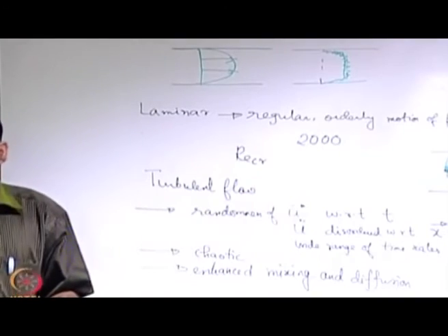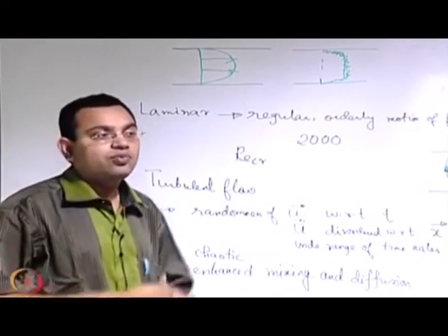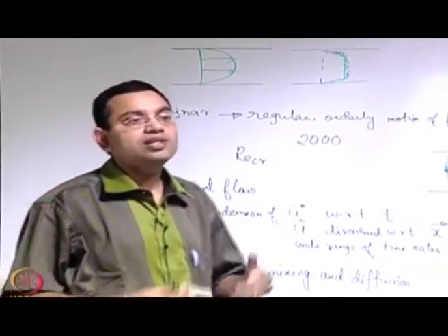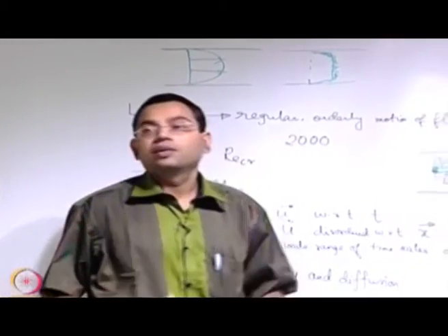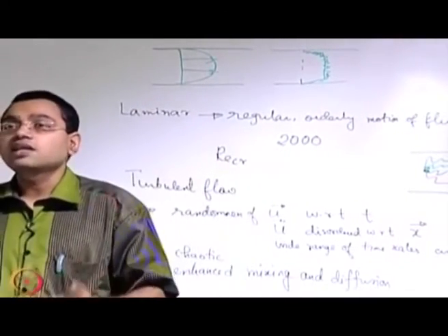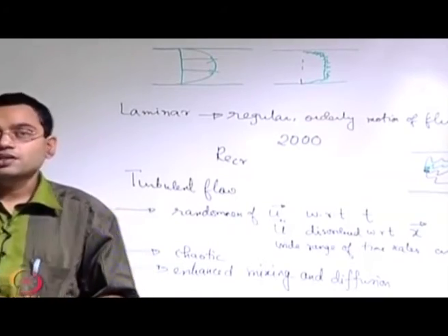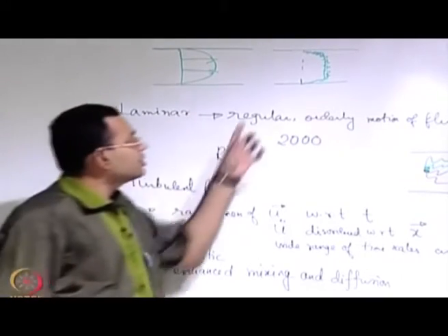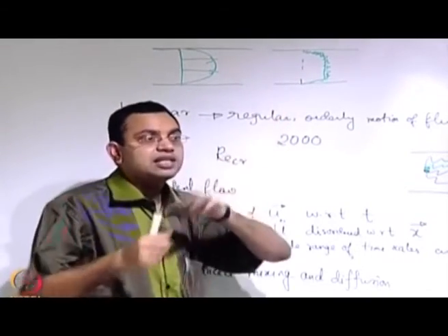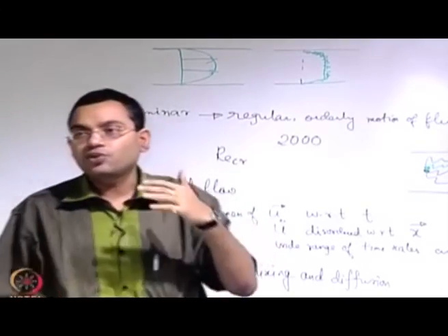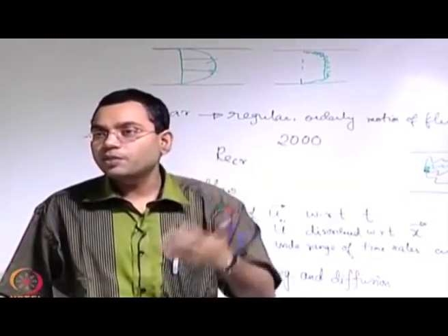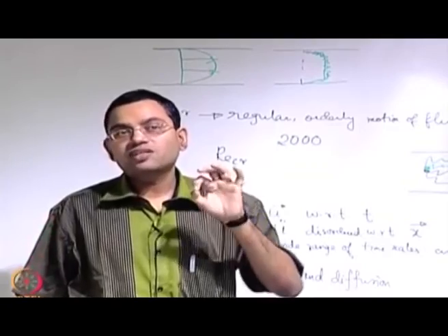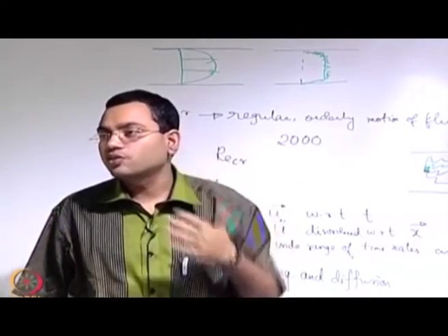So one of the important things is what is more repeatable or more predictable, and that is the statistical property of turbulence. That means you do not just look into the instantaneous properties, because instantaneous properties will fluctuate, and if you repeat the same experiment again and again, because of a slight change in disturbance, those fluctuations will be different.